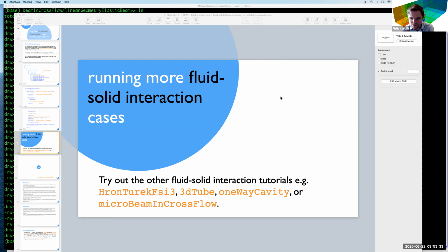Hauger, hello Hauger. Thanks, Philip. Is there a counterpart of the dynamic mesh in the solid part? How do we preserve the volume when moving the solid mesh? That's a good question. In solids, most of the solid models are using the Lagrangian approach. Under the Lagrangian approach, the motion of the mesh is a function of the solution. So the displacement at the cell centers, the motion of the points, is not separate from that. You can't move the mesh separately from your solution field. It just comes from the solution itself.